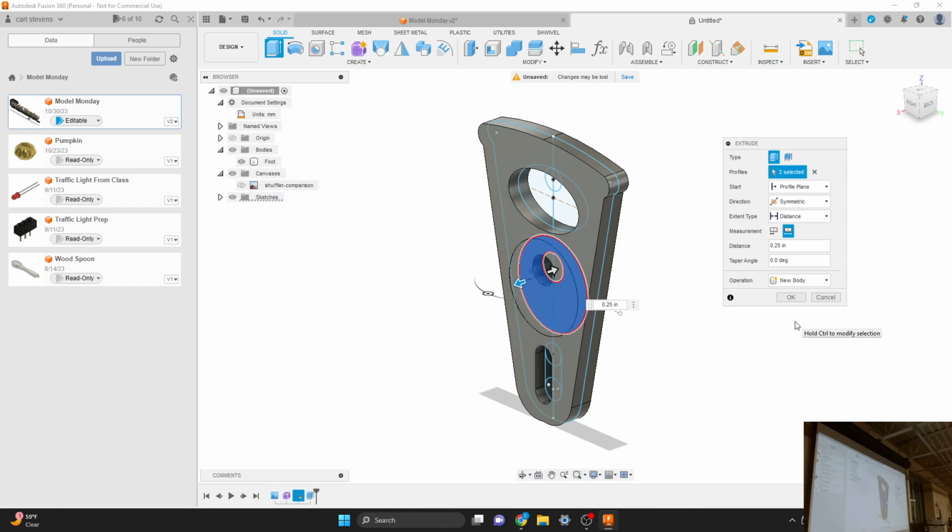So if you click cancel, and then right click on sketch 2 and say edit sketch, and zoom in down there, it's sort of like connected, so you can draw a line, or you can just drag that over. Yeah, you just drag right over. There we go, now we're all filled in. Alright, so finish sketch?